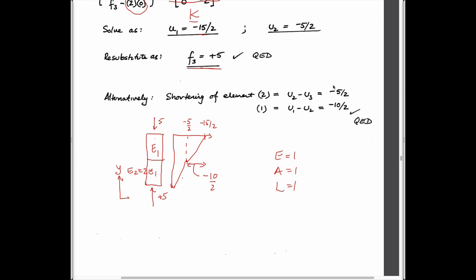This, of course, means that the displacement that we get is actually larger than the length of the element, which is only 1. So that's nonsense, of course, right? It's turned itself inside out. But if E was actually a normal magnitude for a rock, which would be 10 gigapascals, then this would just be 5 times 10 to the minus 10 MPa. And so it gives strange results.